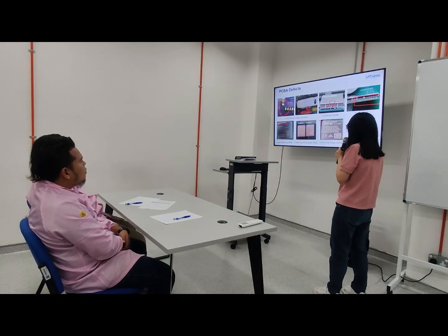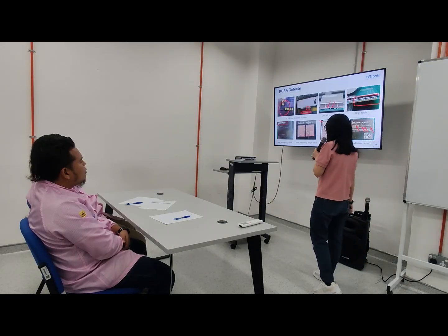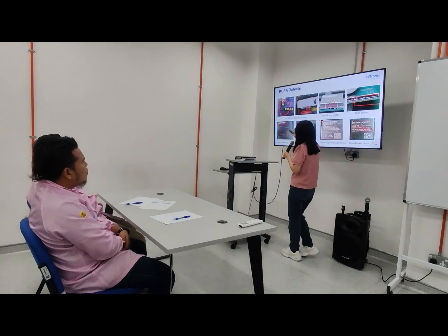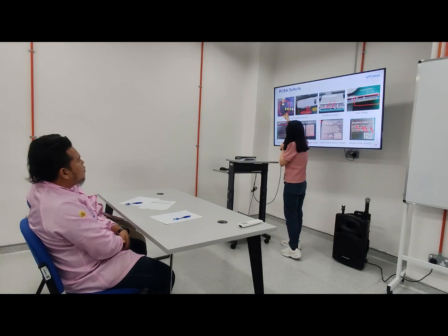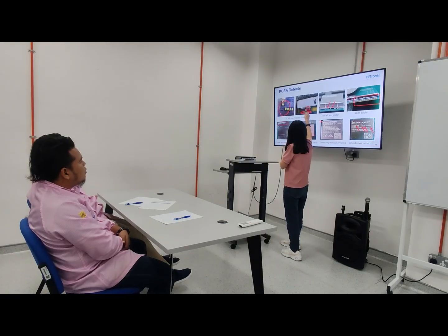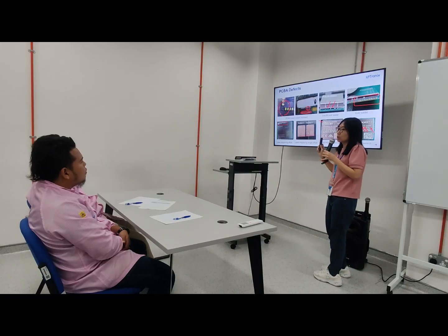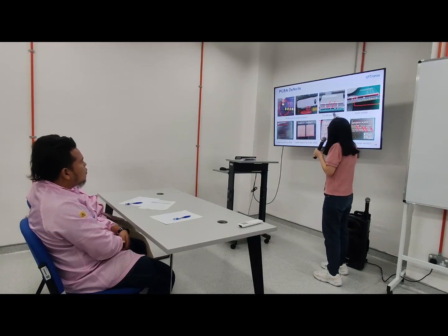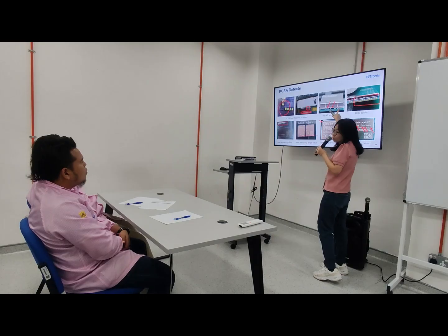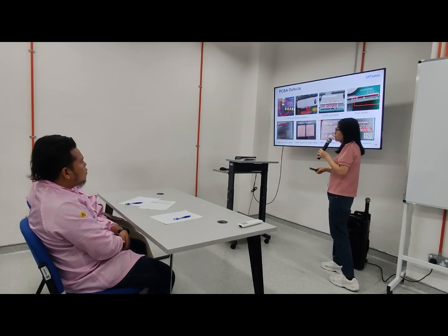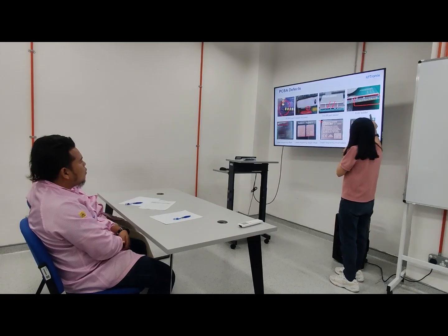Next will be basically copper exposed. Once we see any copper exposed, it cannot be accepted. Here, for example, copper exposed, not the base metal, the copper exposed, totally reject. And then insufficient solder. Here we can see there's solder there, but here, empty. And here's also the cold solder.